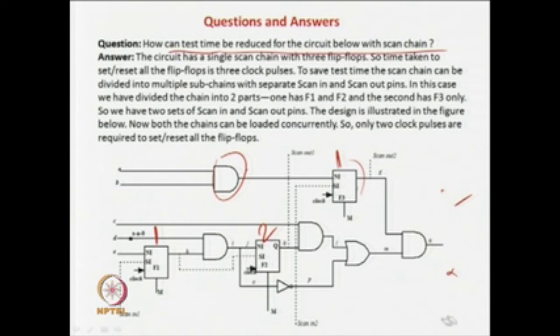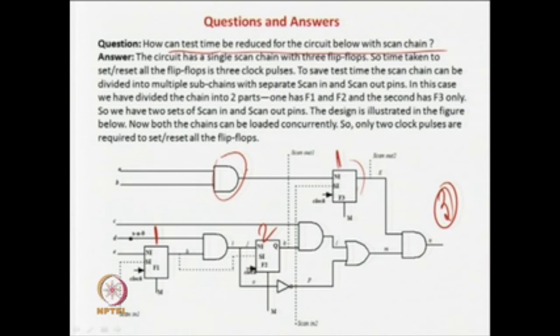But if you are using a full scan chain, then you require 3 patterns to do this. If you go for the time frame expansion method, then your controllability will not be just by zeros and ones, it will be patterns required to control. So, there will be offline complexity, but still you require only 2 patterns to set or reset the flip flops.